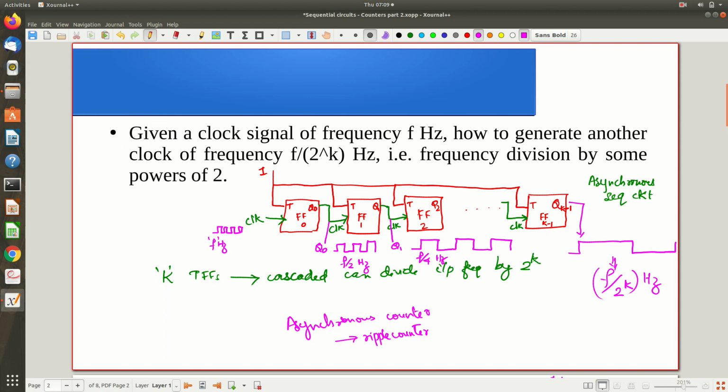So let's observe it. So far in our discussion we assumed that there is no delay. All of them are working very fast and the delay is negligible. But in reality this flip flop is made out of some cross coupled NAND or NOR configuration, and those individual gates will have some delay. Accordingly the whole flip flop will have some small delay, so you can't ignore it completely.